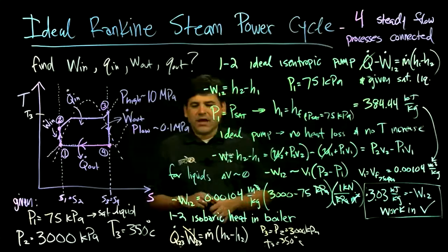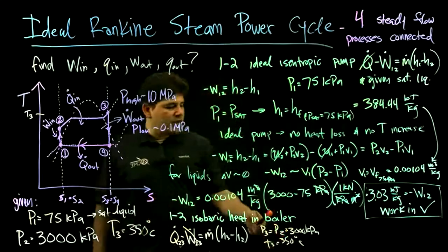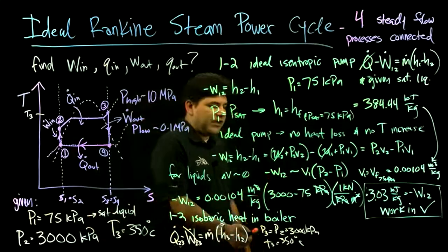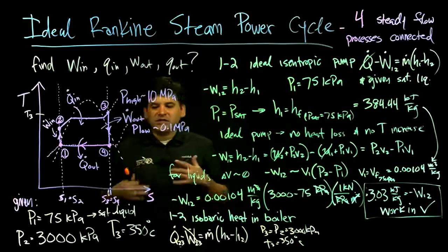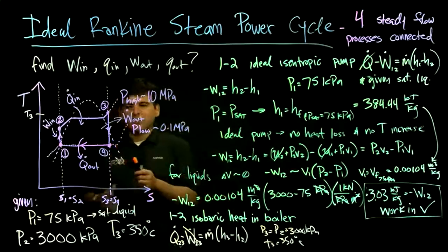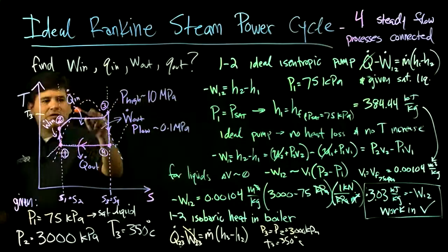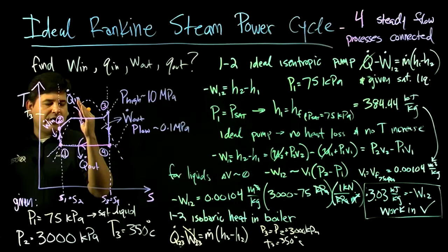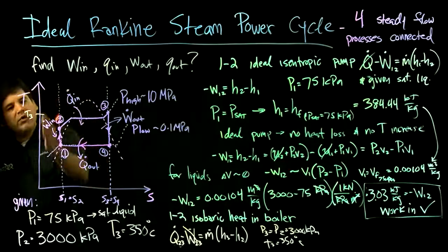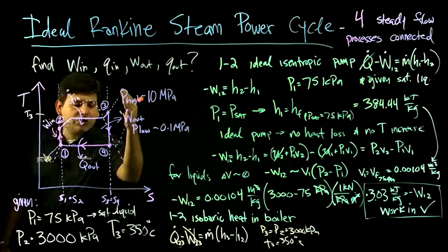So that actually is enough for us to pin down the phase. We know the pressure, we know the temperature. We can test that on the steam tables to see whether it's saturated liquid somewhere on this border or somewhere in between. Depending on where those lie, it's either going to tell us that we're compressed liquid, or we're superheated vapor.